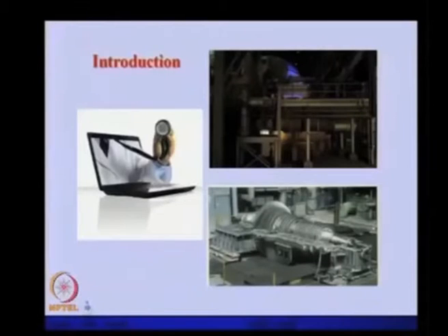So, coming to condition monitoring in industry, obviously in industry we need to capture various kinds of signals, be it vibration signal or temperature, pressure, noise. Those signals we need to store in a computer and analyze, and try to correlate the various kinds of faults which may appear in this kind of machinery, and then we can have some kind of database.